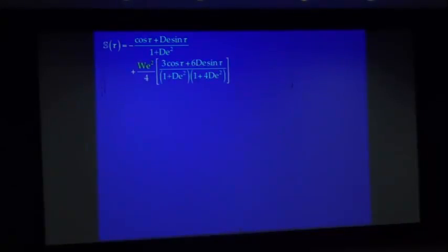Look at the answer for the first one. It just has one harmonic, right? So this is the linear part of the response. Pay attention to the colors here. I've color patterned everything. So look at the next one. It's a second order effect. You can see it's nonlinear in the Weissenberg number. See, Weissenberg number really does reflect nonlinearity.